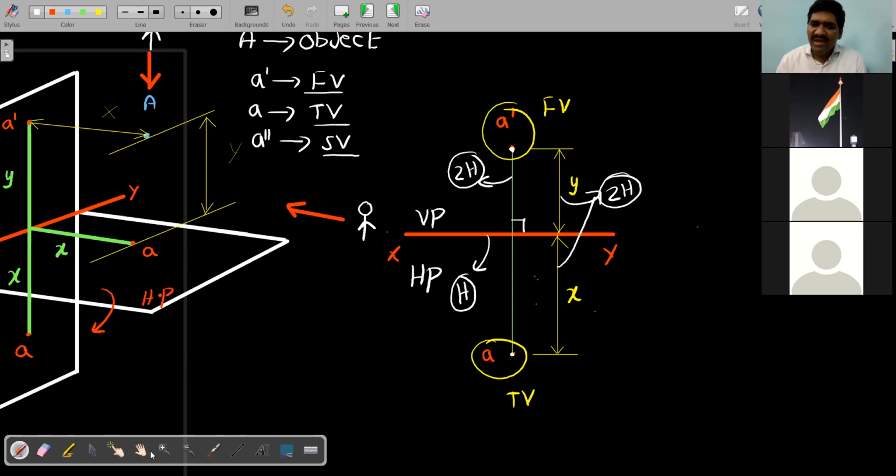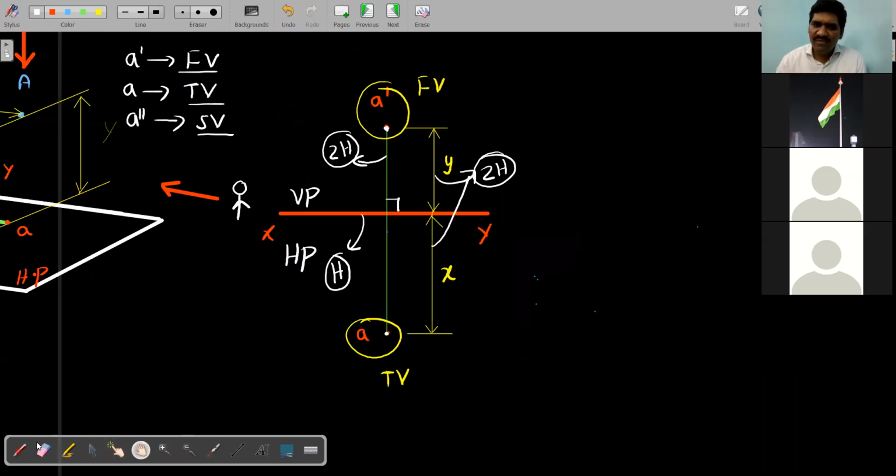Okay, and actually we have 3 pencils, you know very well. So one is 2H, one is H and one is HB. All of you, minimum these 3 are required for engineering drawing. So this becomes thin,